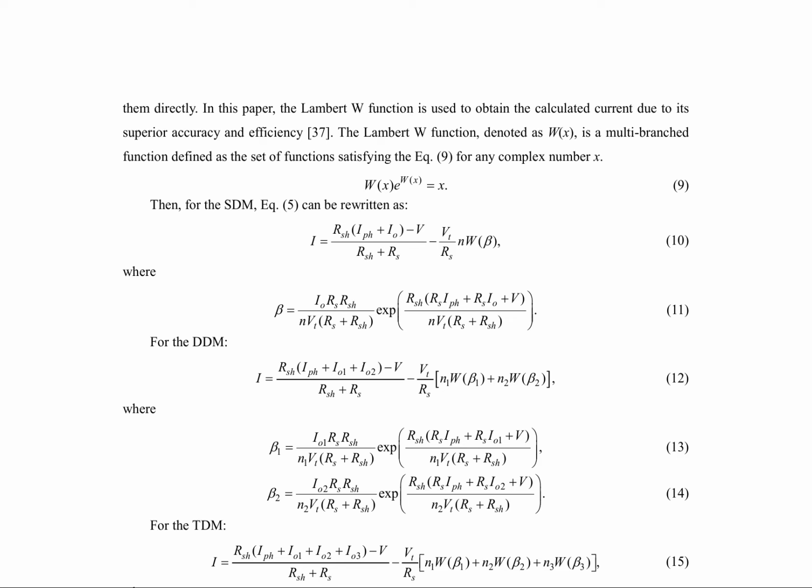Mathematical modeling of photovoltaic cells is crucial for accurate performance prediction and optimization. This study employs the single-diode model, SDM, double-diode model, DDM, and triple-diode model, TDM, to simulate photovoltaic behavior. The Lambert-W function is utilized for its superior accuracy and efficiency in calculating current.